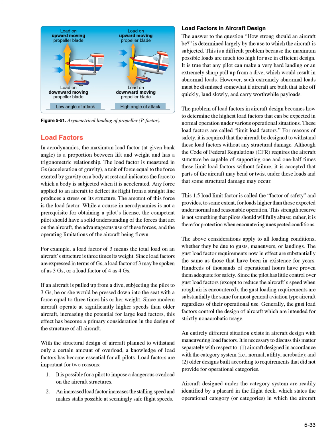Since modern aircraft operate at significantly higher speeds than older aircraft, increasing the potential for large load factors, this effect has become a primary consideration in the design of the structure of all aircraft. With the structural design of aircraft planned to withstand only a certain amount of overload, a knowledge of load factors has become essential for all pilots. Load factors are important for 2 reasons. 1. It is possible for a pilot to impose a dangerous overload on the aircraft structures. 2. An increased load factor increases the stalling speed and makes stalls possible at seemingly safe flight speeds.